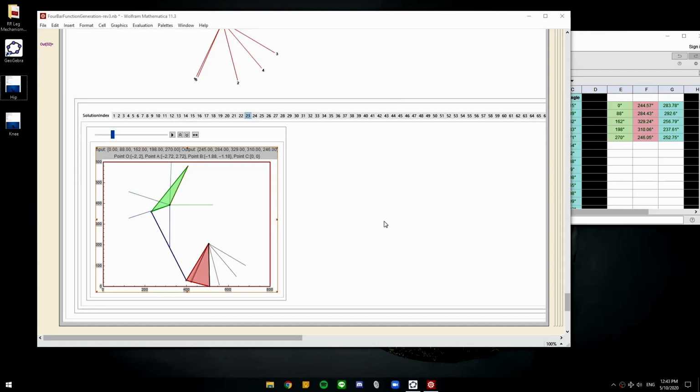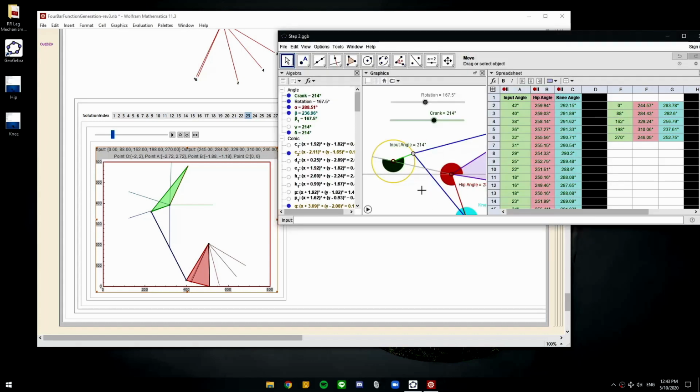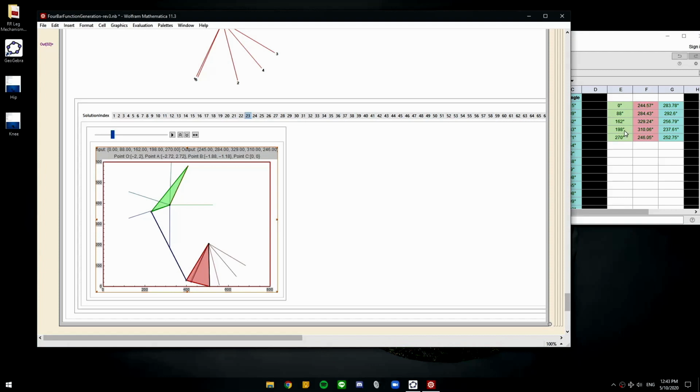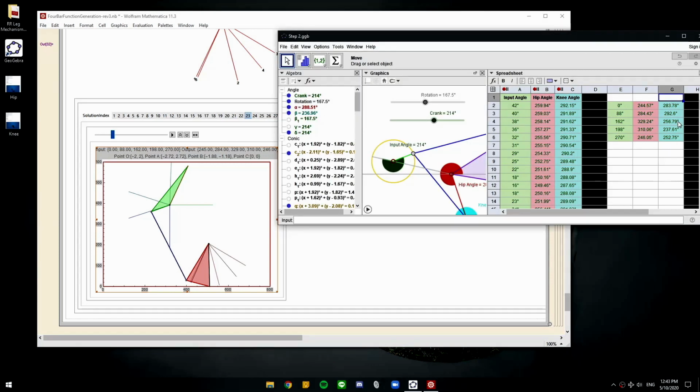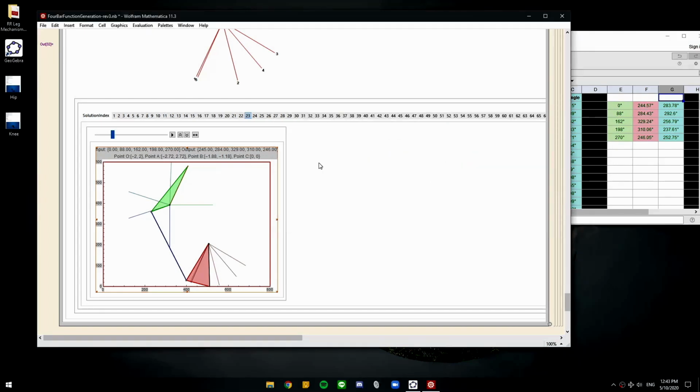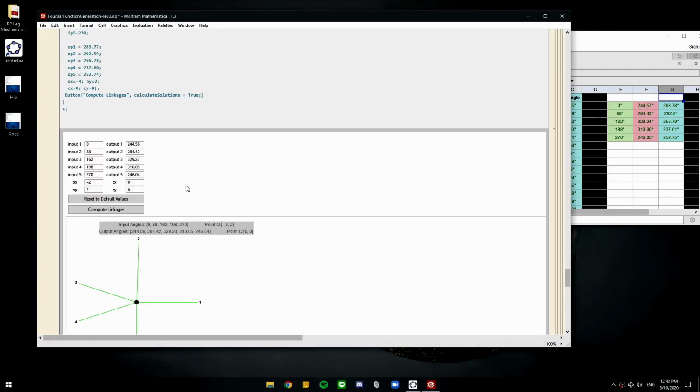And you basically want to do this function generator 2 times. So the first time is what I walked you through. We did the hip angle. You're going to do the second time the same thing, but now for the knee angle. Just remember your input's the same, just your output's different. Again, the important thing to note is make sure your CX CY is the same when you're running the code 2 times. So 1 time for the knee and 1 time for the hip.